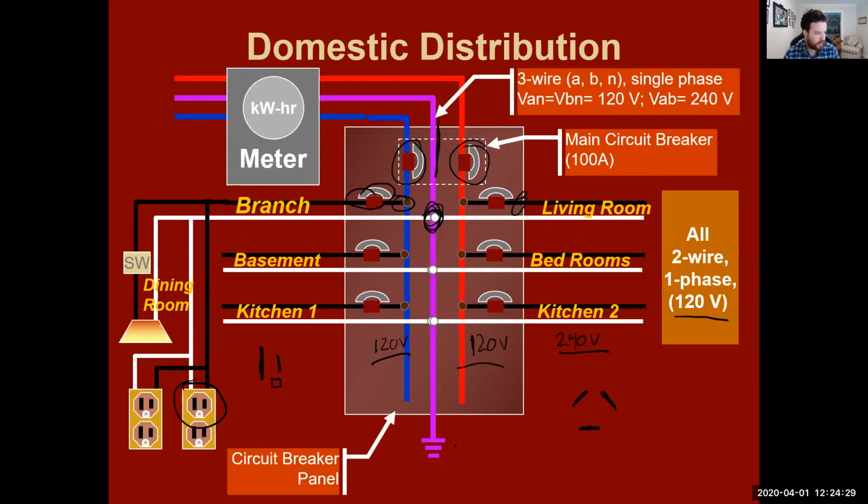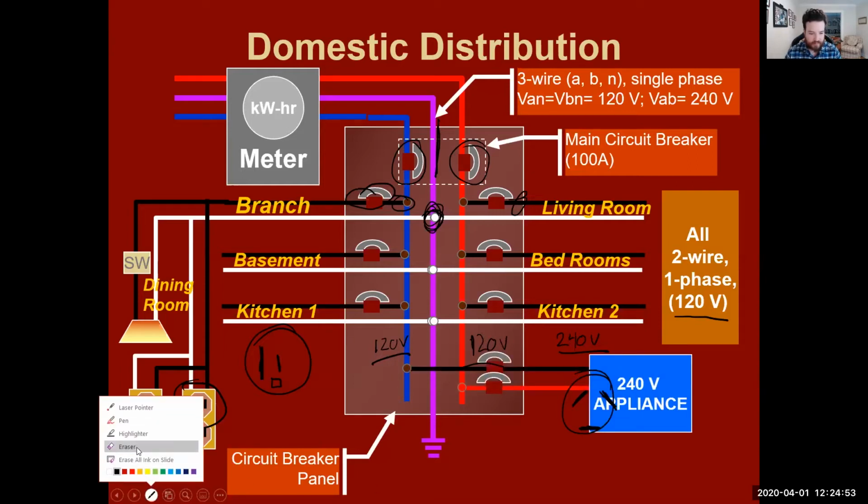Now, they're done that way because, one, you don't want to stick a 120 volt light bulb or whatever into a 240 circuit. All right. It's to protect idiots, which when you do engineering, you figure out that's about half your job. All right. And number two, it's done that way to handle the higher voltage. And the way we gain that higher voltage is through two circuit breakers.